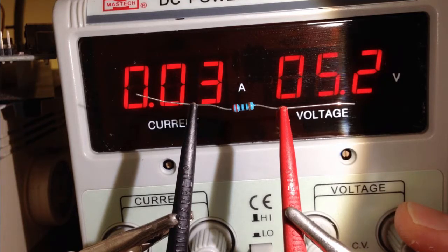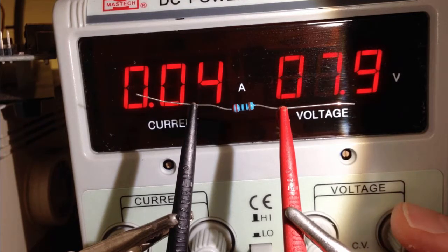So I'm going slowly up, and now I'm at more than 7. And so if you calculate now 8.5 volts times 0.04 amps, here we have a power of 0.34 watts in the resistor. So we have exceeded the rating of this resistor, that's only a quarter watt. If you would touch it now, it would start to get pretty warm. And let's see what happens as I go on with turning the voltage higher.